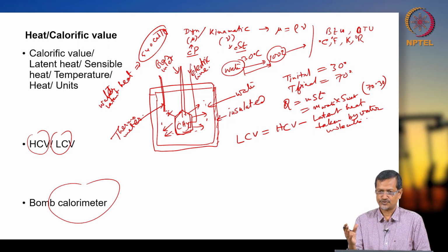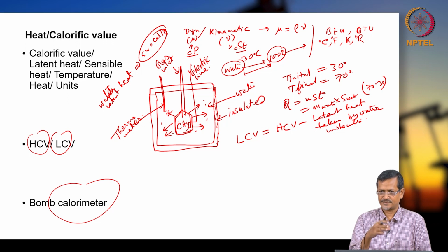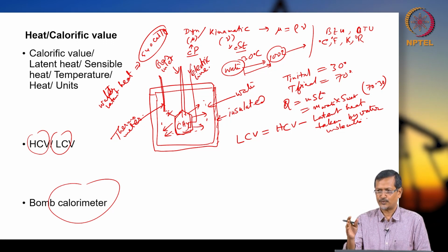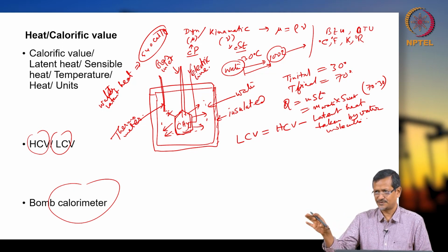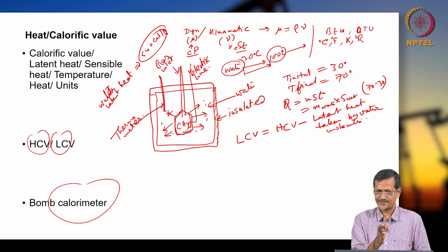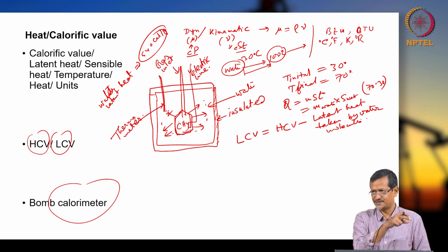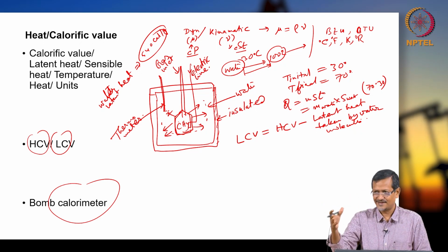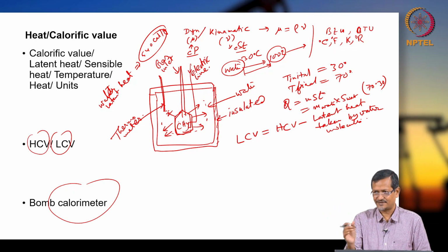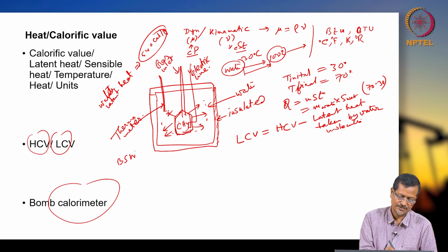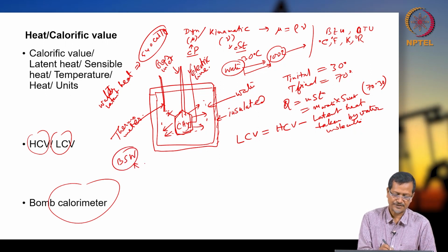Say you are an oil and gas surface production system engineer, and the customer will specify, we do not want water more than this percentage. If you have more than that, they will not buy. You have to check your separator system for a fault, or redesign, or put in a new separator with glycol and other units to remove the water content. They will have a BSW specification, basic sedimentation and water content.